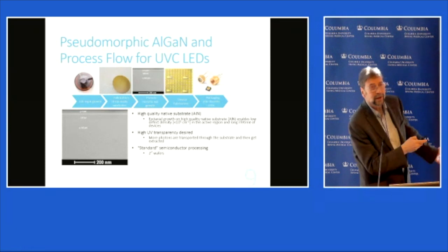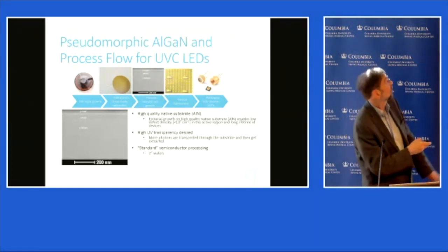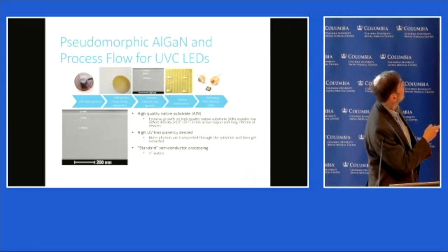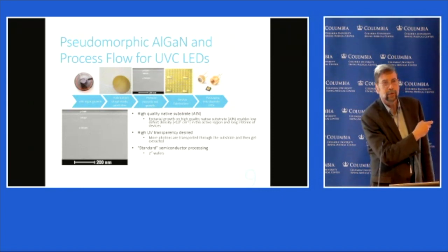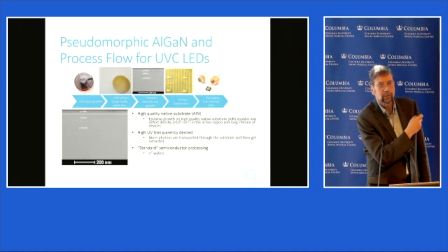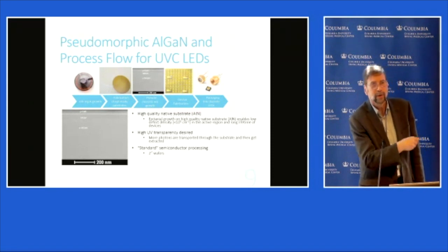And this is looking at the epitaxy when you're growing on a bulk substrate. You can't see dislocations in this kind of material. And that's important because dislocations go through multiple layers, and those disrupt those layers. So if you look at one of those more in detail, if you see a dislocation going through it, you know there's problems in your quantum wells around that.